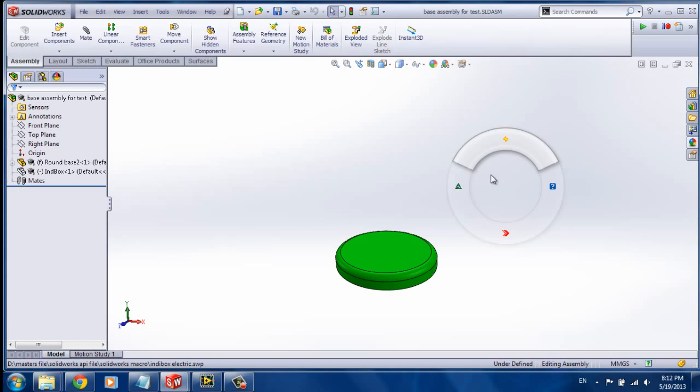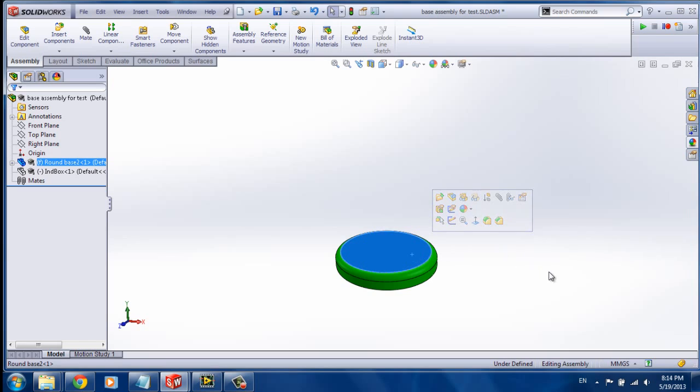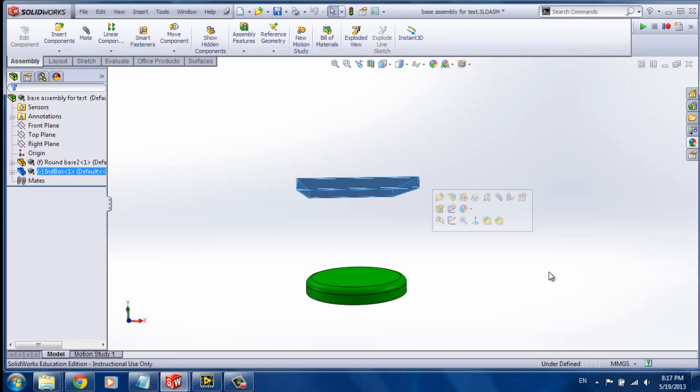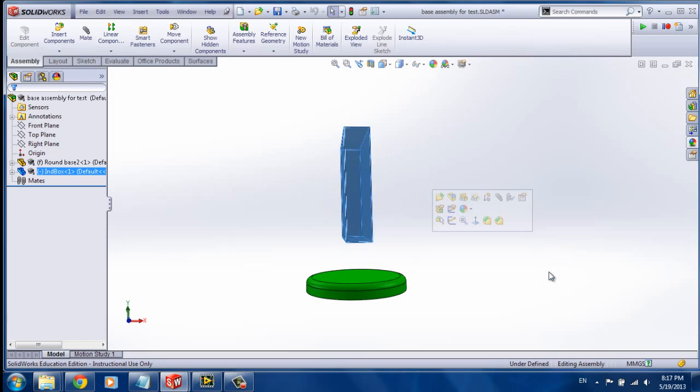First, we define the function property by a customized mouse gesture in SolidWorks. Then we select base as reference part, and the program will automatically initialize an indicator box and set it the same size as the boundary box of the reference base. Then we can move the box freely and position it to an approximate location of the target holder. Then we confirm the location and adjust its size to the estimate size of the target holder.